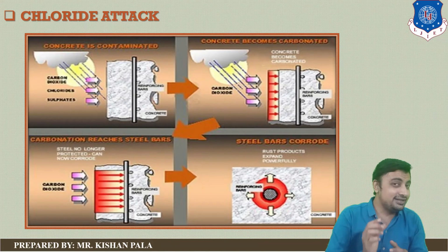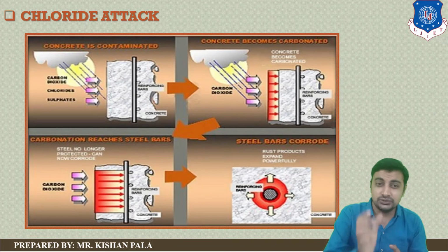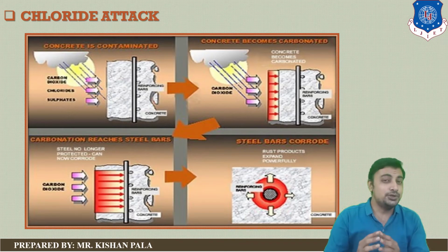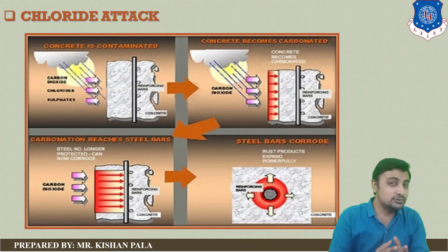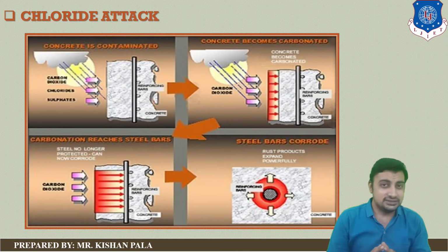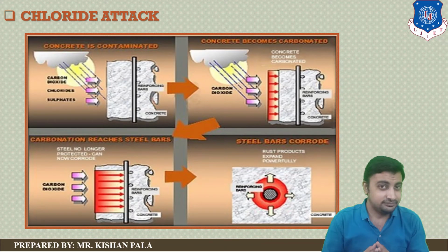As per Indian Standard 456:2000, the chloride content of mixing water should not exceed 1000 milligrams per liter for RCC. So this is all about the chloride attack.